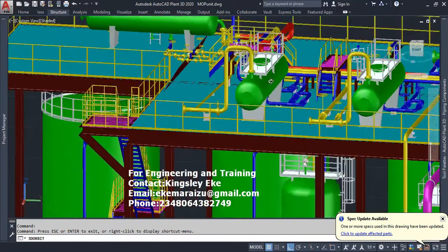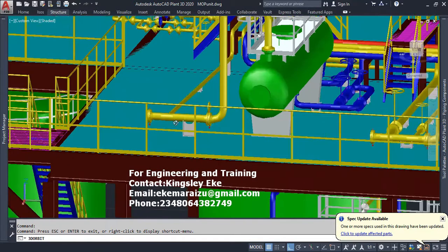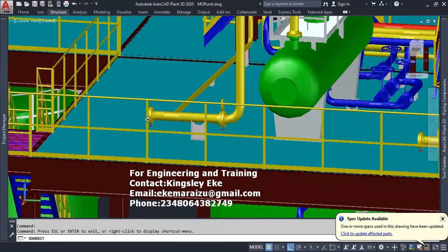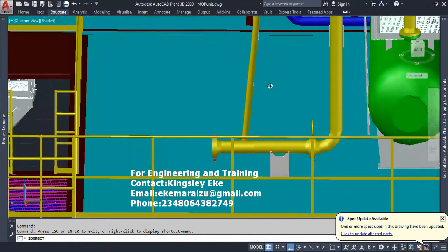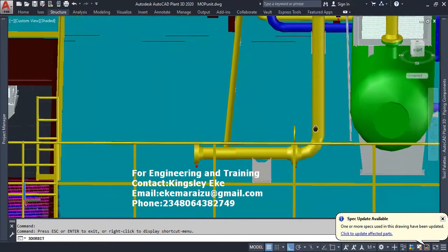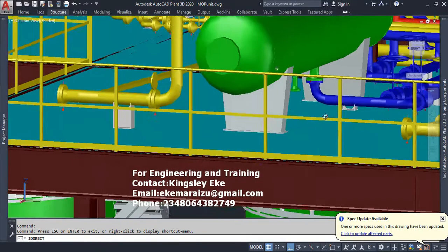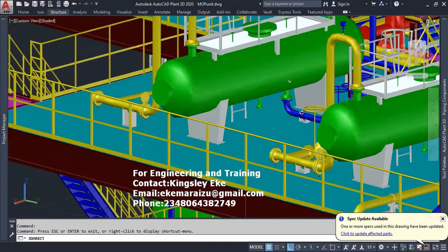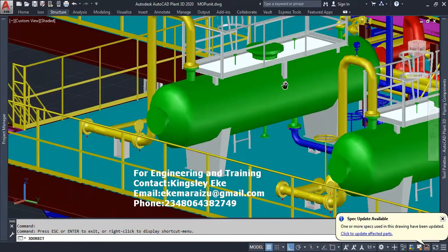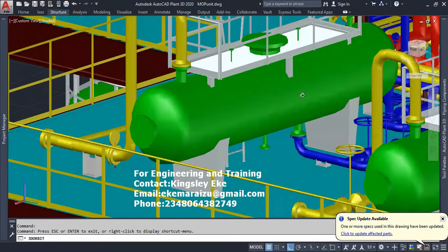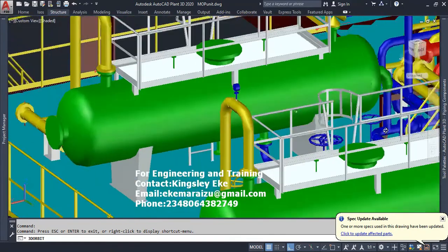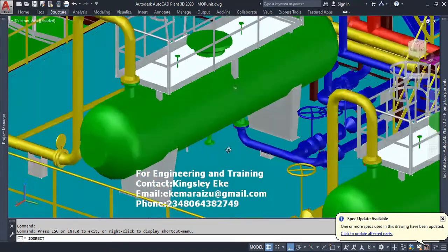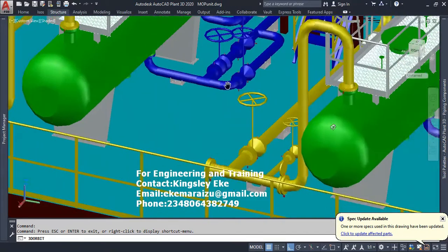So once the facility is in operation, crude from the high pressure header in the inlet manifold is tied into this flange together with high pressure crude from the test separator. They are collected together here and routed into this HP separator. The HP separator can be, for instance, operating at 10 bar, and gas is flashed off in this line and goes into the high pressure gas line, while the liquid is routed to the LP